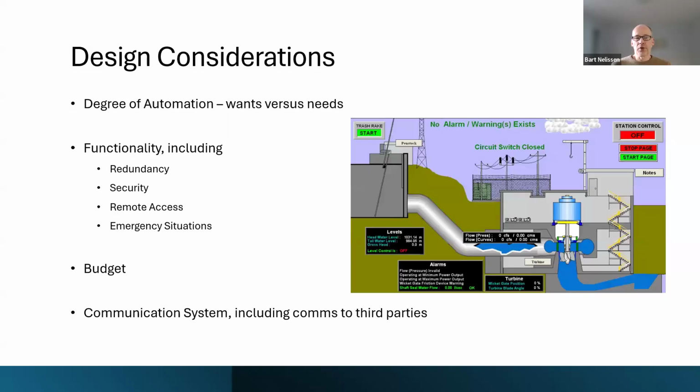Colors are reserved for alarms, so that when something happens that is out of the ordinary, the color on the graphic jumps out at an operator and is easily seen. As pretty as this process graphic might be, it has proven not to be the most productive. But back to the design considerations.